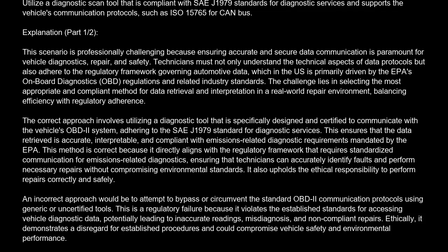Correct answer is A. Utilize a diagnostic scan tool that is compliant with SAE J1979 standards for diagnostic services and supports the vehicle's communication protocols, such as ISO 15765 for CAN bus.